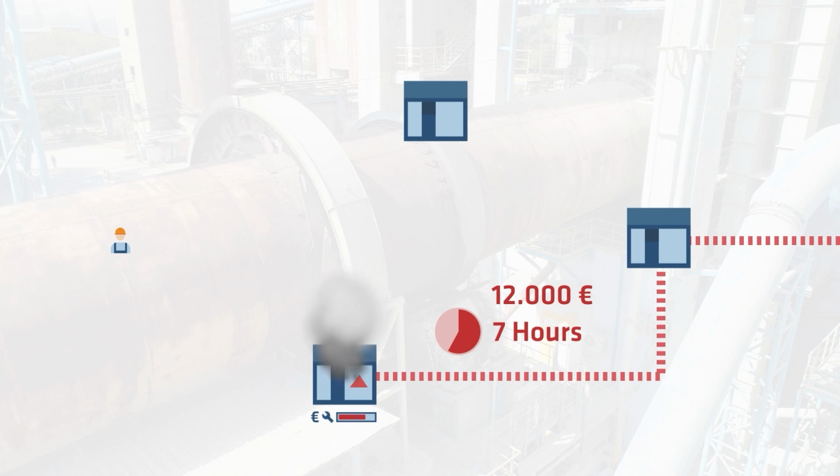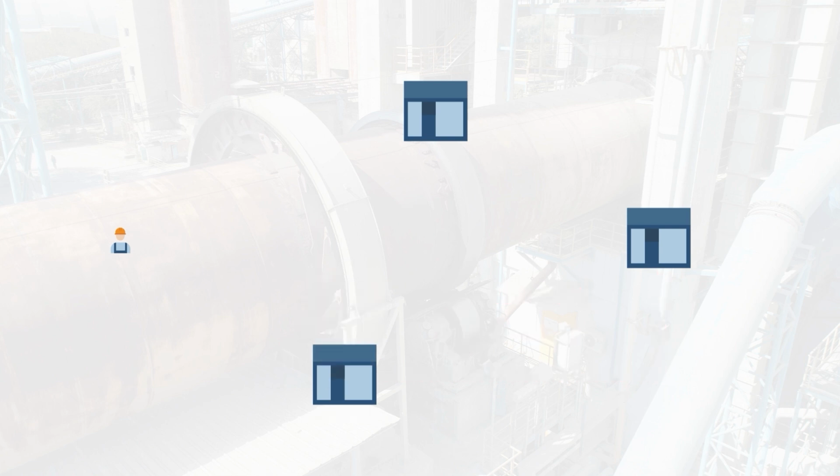How could this happen? Due to an increase in production capacity, this machine was operated with a higher load than normal. Mr. Meyer had not perceived this correctly. As a result, wear on the bearings accelerated and the damage occurred.